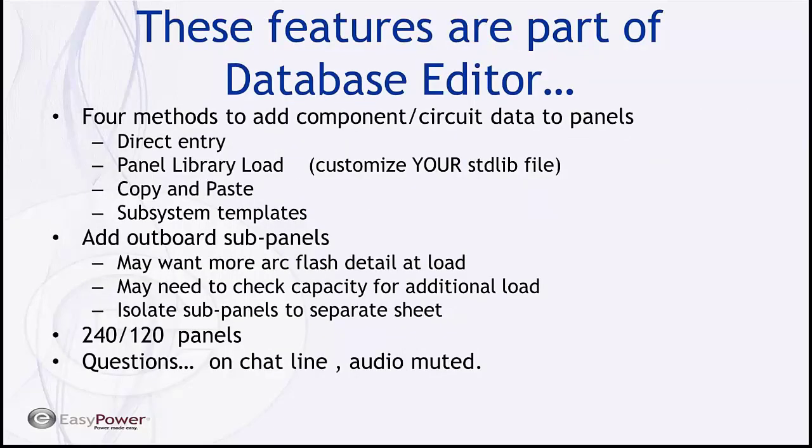There are four basic data entry methods to add component or circuit data to panels themselves. There's direct entry, which I would assume most users are exposed to or experienced with. There's panel library load, which requires customizing your ST standard library file, copy and paste, and then subsystem templates. We're going to go through examples with all four.